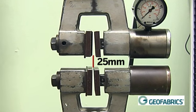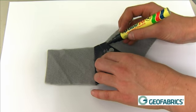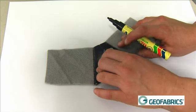Jaws are set up on a tensile machine with a 25 mm gauge length. The two jaws measure 50 mm by 75 mm, with the longer dimension perpendicular to the direction of application of force. The specimen is drawn on using a template to mark the top and bottom edges of the jaws.